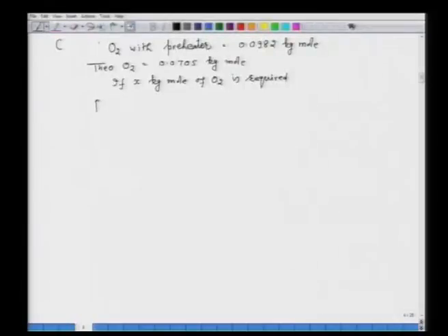So, now we write down again the products of combustion composition. So, POC, say excess oxygen, that we have to keep the same as the problem illustrates, that is 0.0277, mind you, they are all in kg moles. Now, nitrogen will be equal to 0.369 earlier.